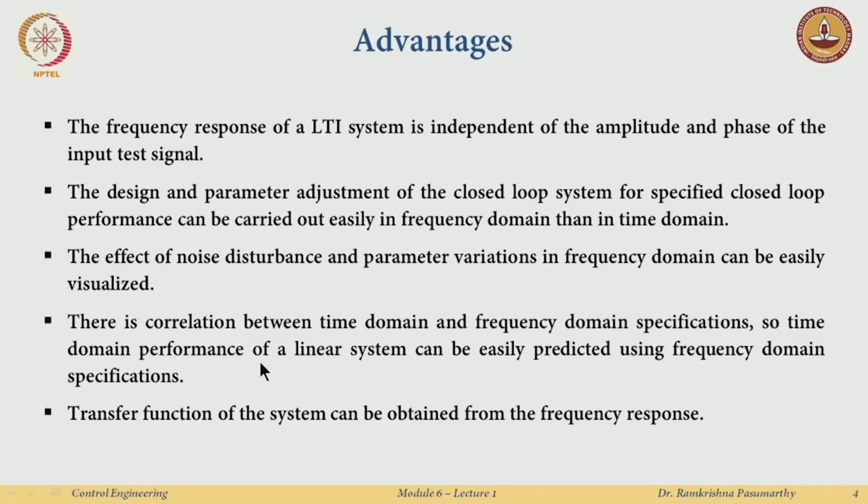Another thing I could do is, if I do not know the transfer function of a system, I can give it signals of varying frequency and, based on the frequency response, easily estimate the transfer function of the system. You may also say, why not just look at the step response of the system to get the transfer function, because the step response included zeta and omega n.